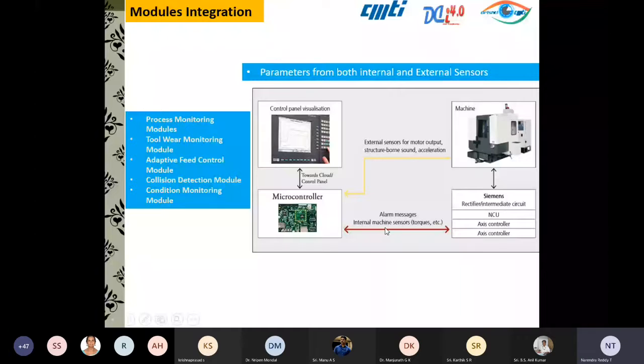As you are taking from the machine controller via Ethernet, you take it to your server, it comes to the client, and finally you represent it in your dashboards. If it is a cloud, it has to go to the internet, and from there you publish your data in the form of dashboards. But this whole process takes about 0.5 seconds of latency. It means that if you want to take corrective action on this machine, or control the machine, you can expect a delay of 0.5 seconds. For modules where we don't want quick actions, you can use M2M connectivity. You can just request OPC UA and do all the solutions which go beyond 0.5 seconds. Okay, and there is another problem.